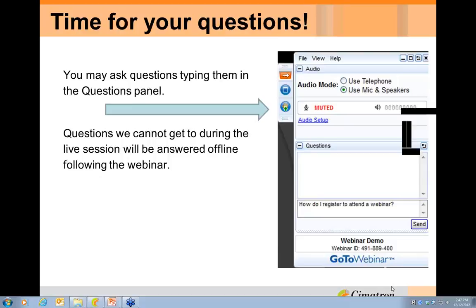This question says, once you have done a change at the insert level, is it still possible to go back to the top and change the work file again? Yes. Here's the thing. I showed our options in a certain order. Started with the top down and talked about, well, let's put a change in the middle for various reasons, or let's put a change in the end. Once you move down that list, you really should stay there. And I think it's kind of obvious. If you're taking a change and comparing it to the work file, it should always be up to date. But if you're moving it down into the bottom of an organized tree, of a history, it's a bad idea then to say, well, for the next one, let's shove it in at the top, because it's not going to recognize that new geometry until the end. So you can mix and match, but if you go in one direction, you really should stay with the last option you picked.